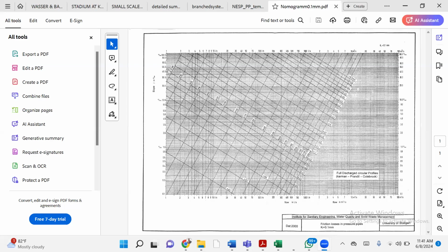Like in sewer design, when we start sewer design in 4 weeks' time, it says that you cannot use any pipe less than 6 inches, 150 mm, based on German standard anyway. If you see anybody laying sewer pipe with 4 inches, 100 mm, it is absolutely wrong. You can use it in building services, but not in centralized wastewater networks. The standard also says that you must put a manhole at intervals of 60 meters, not more than 120 meters.